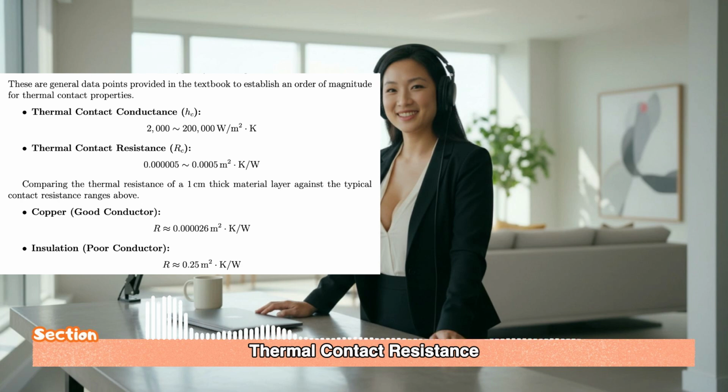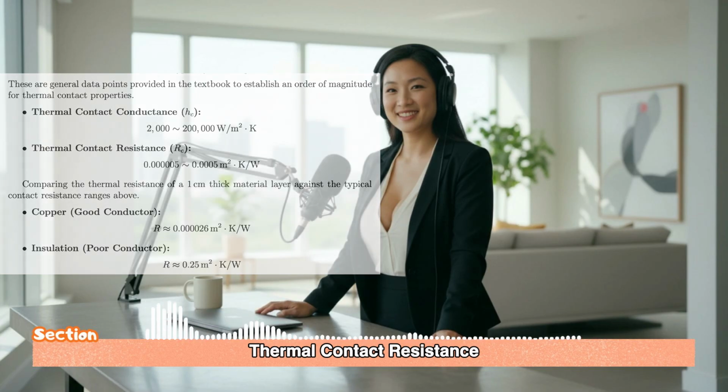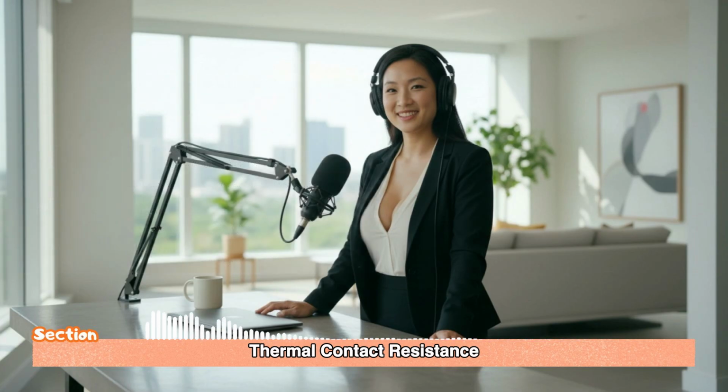This is the critical takeaway. For good thermal conductors, RC can absolutely dominate the heat transfer path. If you are building a system designed to move heat efficiently, like a cooling system for a computer, that interface resistance can completely negate the benefit of using copper in the first place. It can. The bottleneck shifts from the conductor to the air trapped between the conductors.